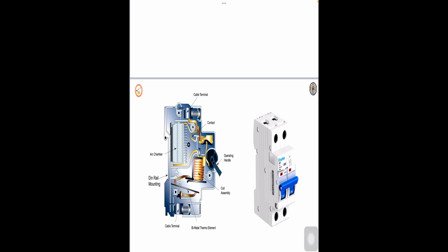It has certain demerits also. Compared to a fuse, the cost of an MCB is greater, and distribution cost and equipment laying is also higher when compared to fuse boards. Slow tripping sometimes, aging and wear and tear, you need to replace them. It will not protect against earth faults and it is vulnerable to heat. MCBs are also used in commercial, residential and industrial settings.